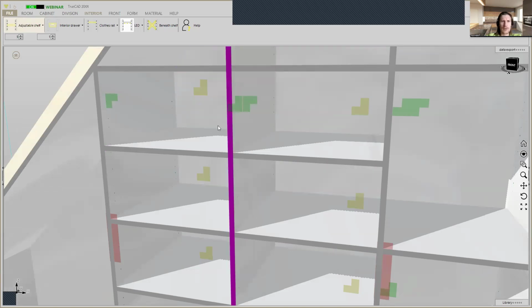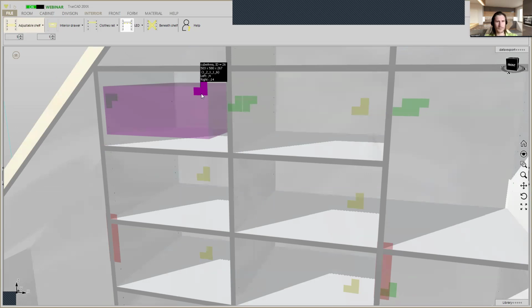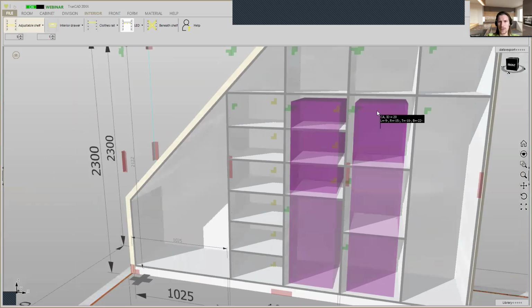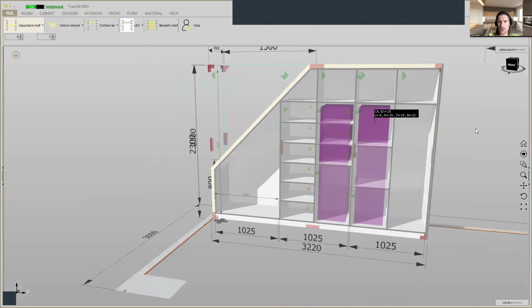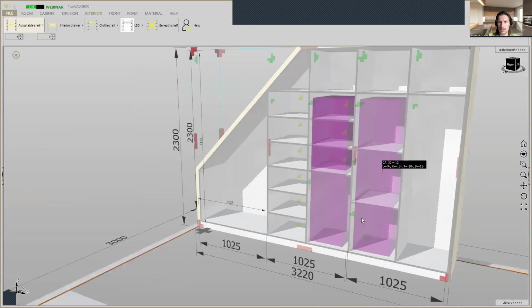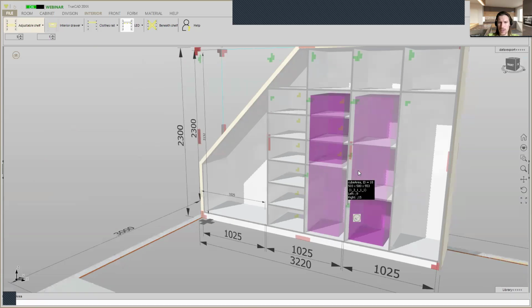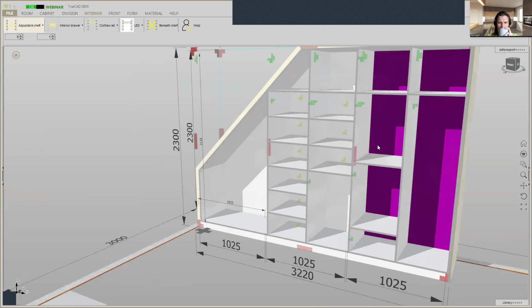The size of the area you see when you go with the mouse over the smart click for the interior shelf. Now you see the height is a Z value, it's 267, and 267 is also the size of this area and should be also for this area. So we click on here, change the height to 267, and the same here.